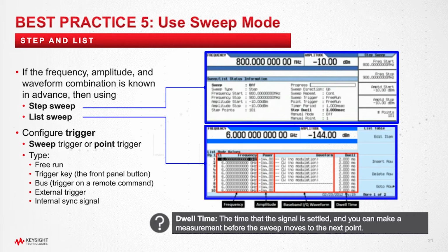The step sweep offers a linear or log progression from one selected frequency and amplitude setting to the next, paused at the linear or log spaced points along the sweep span.